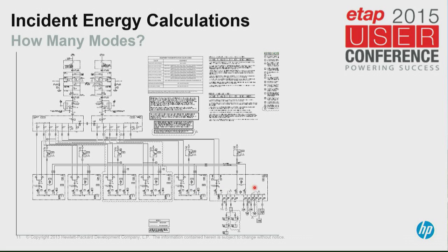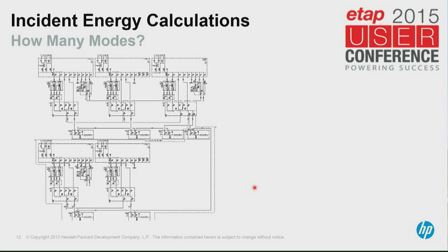Then we have what we call a maintenance bypass and load bank substation. Basically, the purpose of which is to be able to take any generator, any UPS, and load bank it individually from a single common load bank. At the same time, what you're going to see in the next slide is that we can put the critical load, because we don't want to take it down, remember, on generator bypass, and we can load bank the unit substation that was normally feeding it, all through a series of loops and bus configurations, which you can barely make out here.